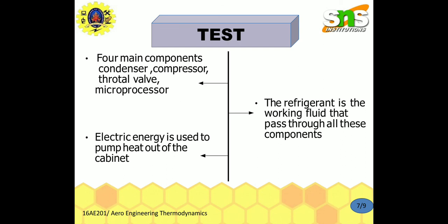The COP of a heat pump is given as the heating effect divided by the work input. Both the COP of a refrigerator and of a heat pump can be greater than 1. Combining these two equations, the COP of a heat pump is equal to the COP of a refrigerator plus 1, for fixed values of high heat value and low heat value.